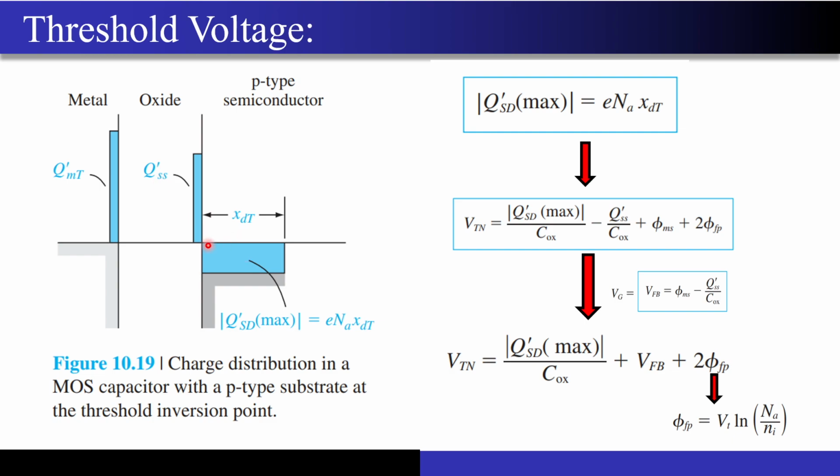Now what was happening was that your depletion region width kept on increasing. Now it maxed out, right? And now you started having the inversion layer, that is this gray region. Just imagine this small gray region that I'm pointing at over here. So now this inversion layer density, because you got the electrons over here, right? These electrons and the depletion region's negative charge densities are balancing out the positive charge density that you have at the metal, because you applied some positive voltage at the metal, right?